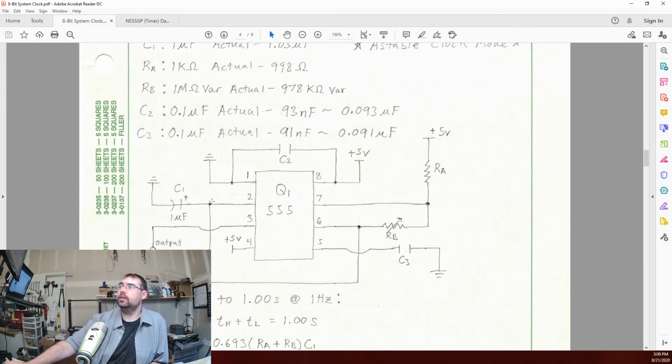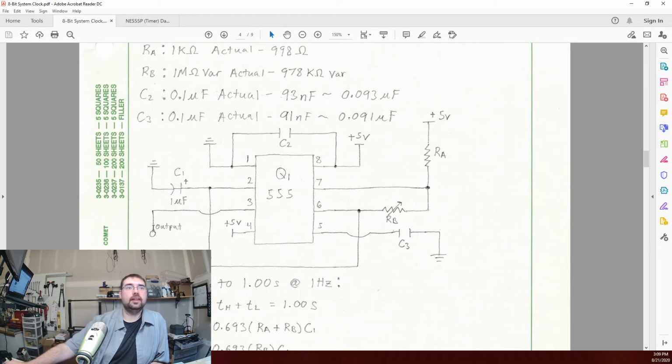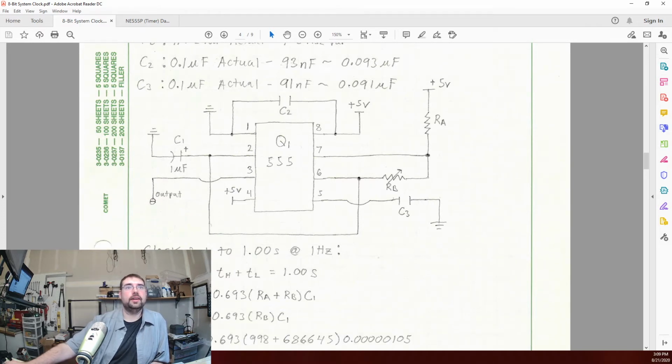Pin 2 will have a little splice. When you see a little dot here, it means that it's also connected. So it's connected here, comes down, and then connects up to pin 6. Pin 3, when you see this, at least on mine, that means that it's not connected. Think of it as just a wire going over. That's our output. That's going to be our out to our clock. This is how our clock is going to connect up to our computer. In reality, what we're going to be building is going to have a little more.